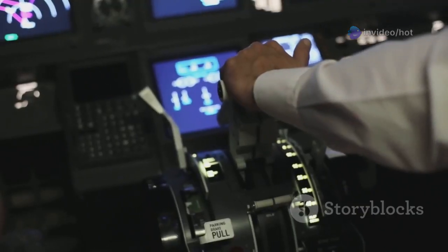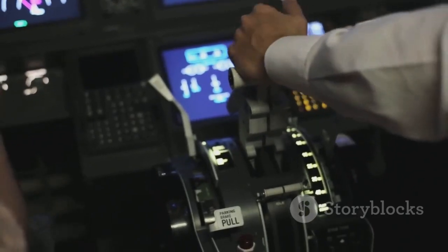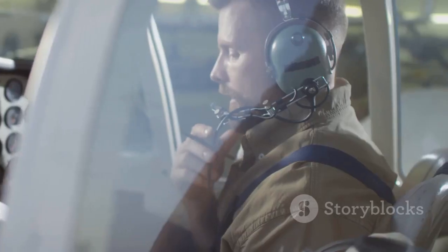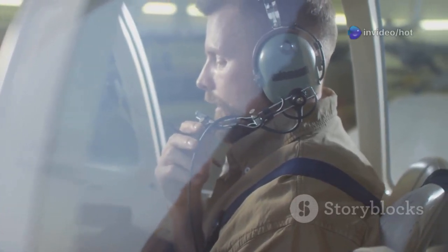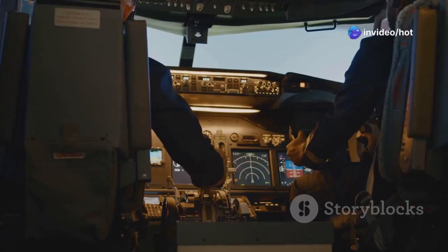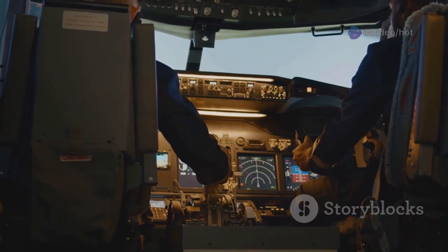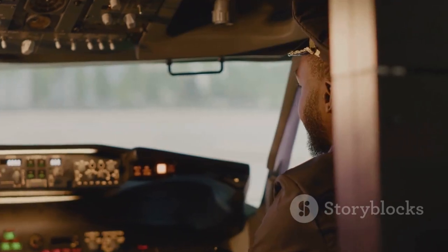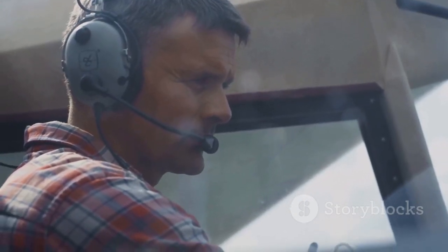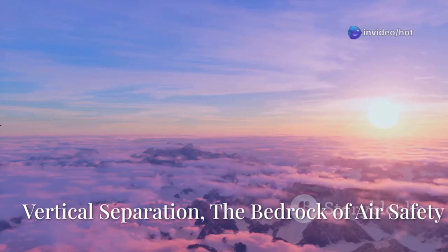A pilot might mistake flight level 230 for 250. Read back and hear back procedures are crucial here. Pilots must read back the clearance exactly as heard. Controllers must listen carefully to confirm it's correct. Fatigue, distraction, or high workload can contribute to these errors. Complacency can also be a factor, especially on familiar routes, assuming a standard clearance without full attention.